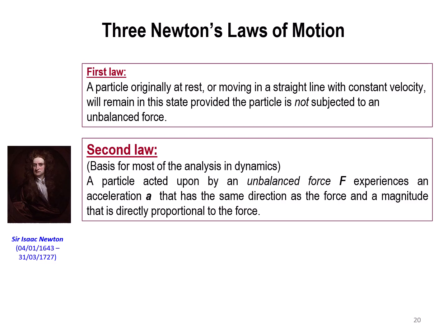The second law, which is the basis for most of the analysis in dynamics, says that a particle acted upon by an unbalanced force F will experience an acceleration A that has the same direction as the force and a magnitude that is directly proportional to the force. So when you push the particle, it has acceleration in the same direction. The higher the force, the higher the acceleration.